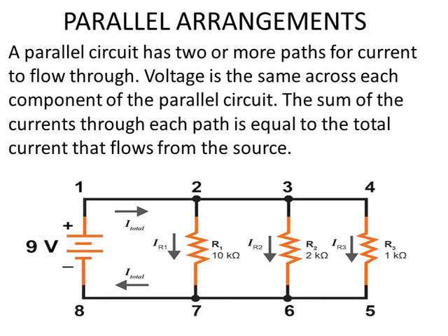Now, for this particular arrangement, the same voltage is across all the components, and that's why it is a parallel circuit. So one thing I need you to understand is that for series arrangement we have just a single path. For the parallel arrangement you have 2 or more paths. For series arrangement you have the same current flowing through, while for parallel arrangements, what they have in common is the voltage, unlike the series arrangement.